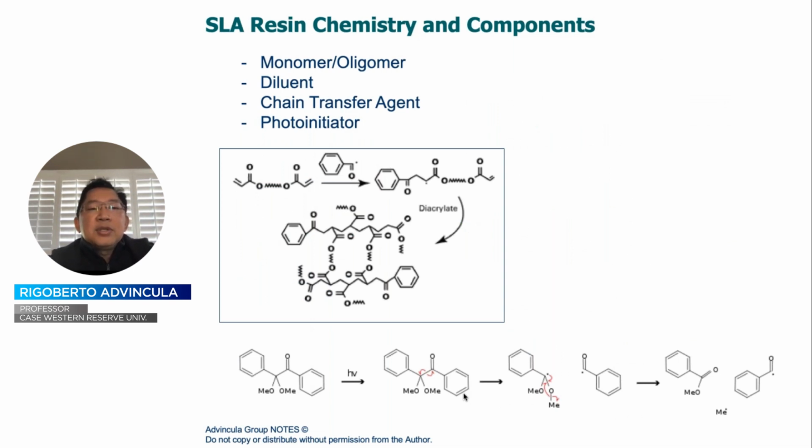Now, talking about the chemistry, one can classify the compositions as based on the photoinitiator, presence of the cross-linking oligomer, a monomer or diluent monomer, and then the presence of species like chain transfer agents or even photosensitizers. So the photoinitiator is something that is sensitive to the light source. In other words, this can be wavelength dependent, meaning one can talk about UV wavelength or visible wavelength to basically break up species that generate the radicals. It is the radicals, or the presence of it, that causes cross-linking.